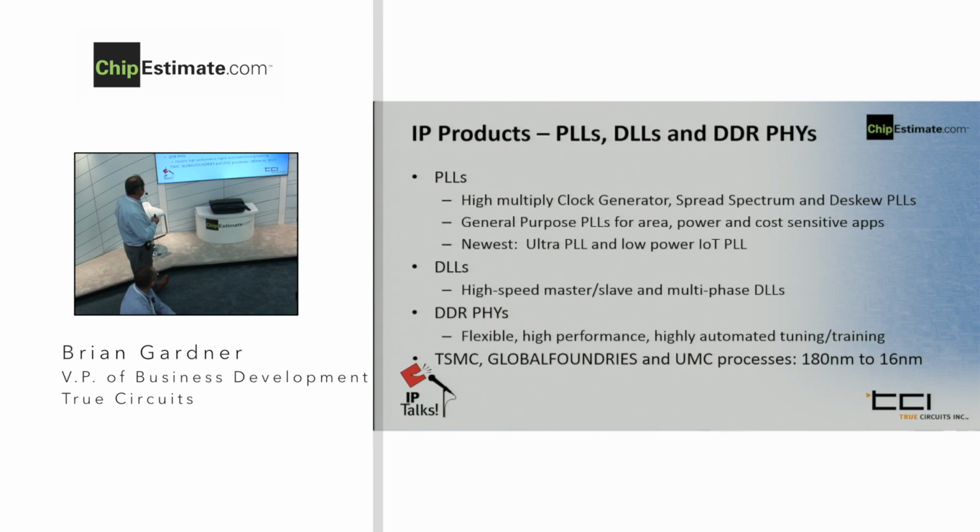We have, like I said, just about every process variant of TSMC and Global Foundries and UMC that you'd find, even back to the older processes. Because we do things in an automated way, we can actually produce a modern architecture in an older node. And that could be interesting because there's a lot of energy in some of the older nodes because of the IoT world, where you don't need something that sophisticated. In fact, you might even want to take advantage of better analog properties in older processes, or you might have some kind of sensor technology that marries itself nicely to an older node.